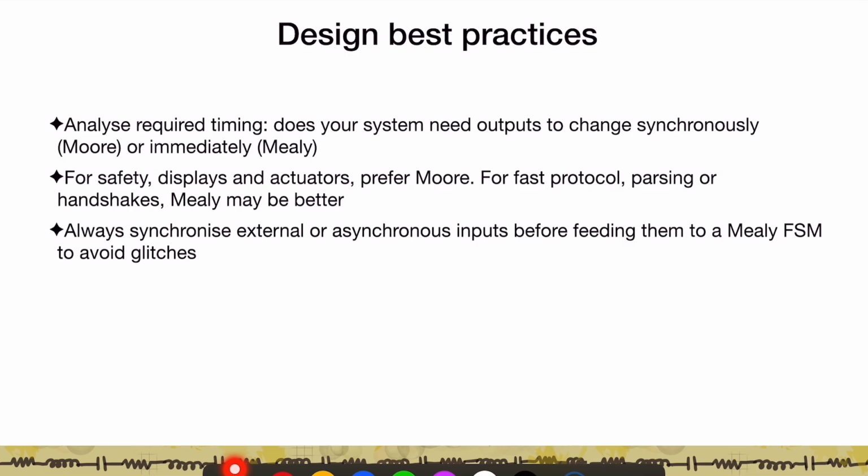And it's always a good idea, if you're implementing a Mealy FSM, to synchronize the external or asynchronous inputs. That way you reduce the probability of glitches in your design.